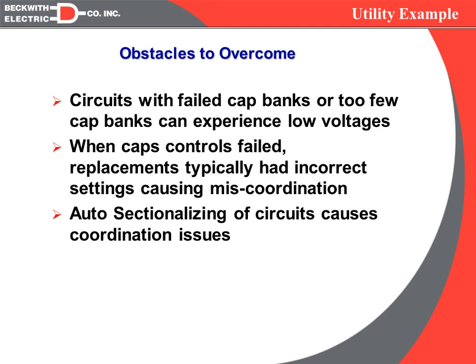But with that, there were some obstacles. Number one is they are using the negative X to supervise the capacitor bank, so that if you get too far leading, the regulator or LTC will raise the voltage and trip a bank off.